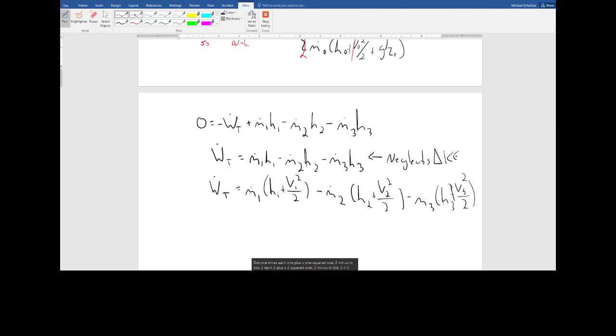And actually, if I look at those units, I know that h, if I look it up in the textbook tables, is going to be in kilojoules per kilogram. But now this kinetic energy term stuck around. My spidey sense started tingling. Here I get velocity squared, which is meters squared per second squared, which is the same thing as meters per second squared times meters.